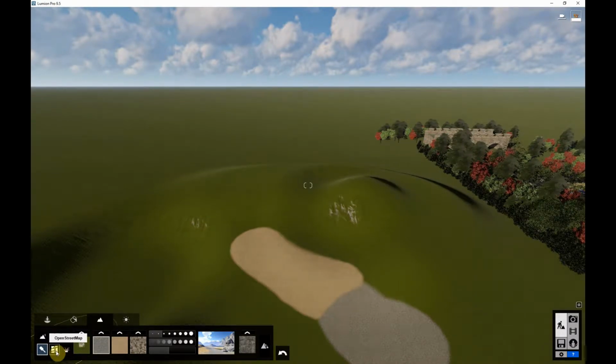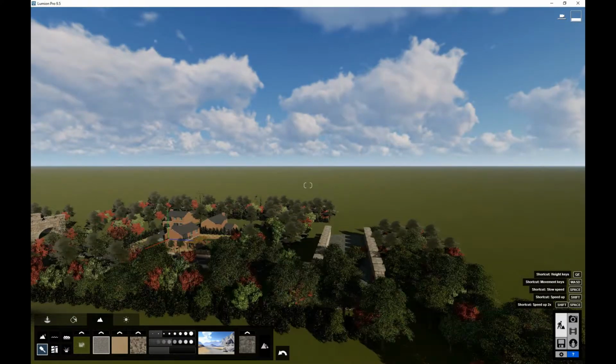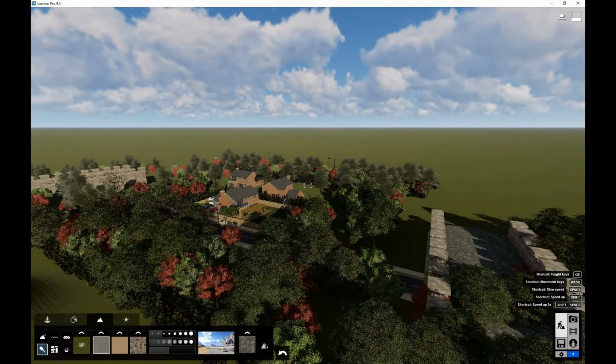And then lastly in here we see OpenStreetMap. This is again a simple contextual tool similar to Google Street Maps, where you load in a plain block model of a particular area of the map, and this does cover the entire globe as well. And you have the ability here to turn objects on and off, such as waterways and pathways, or the landscape itself, and then you get the 3D contextual blocks that you can adjust the size of as well, just to add a little bit of something into the scene.